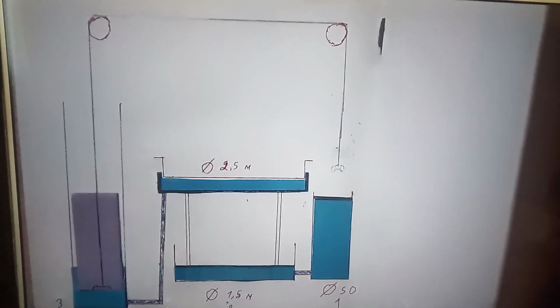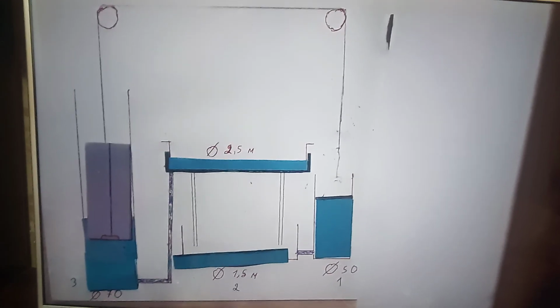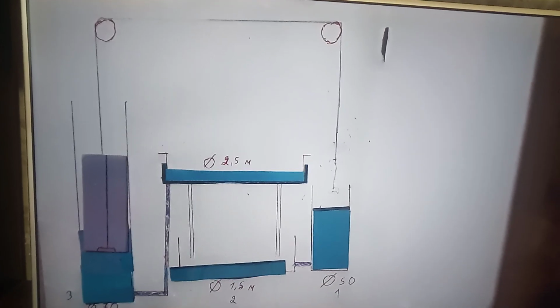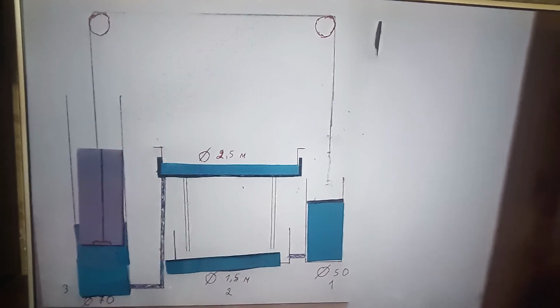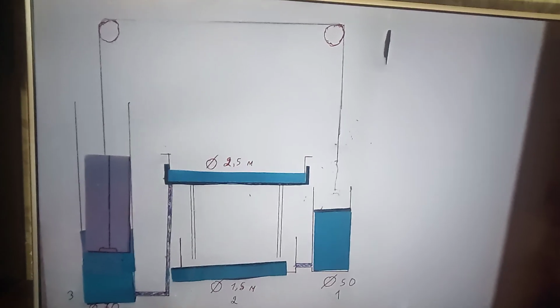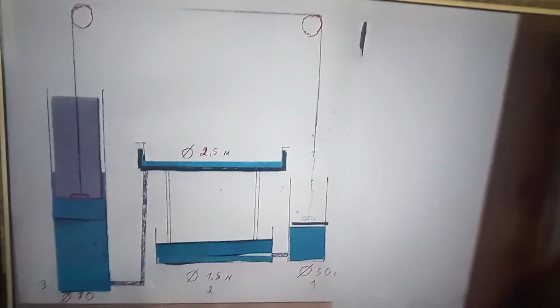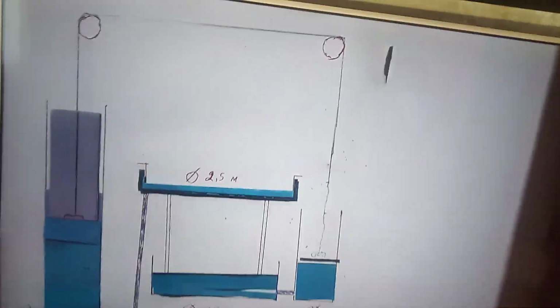After the valve opens, the float will lose buoyancy and begin to move down. The liquid around the float will begin to flow inside it through the open valve. It will flow inside by 17 centimeters. Nothing prevents the liquid from flowing in, since there is a hole in the float at the top and the air will be freely displaced.